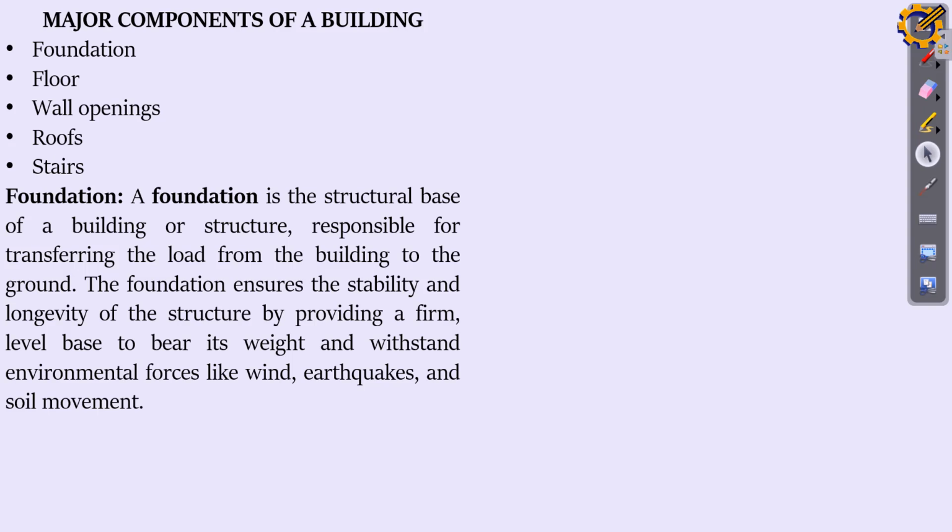Imagine you want to build a structure and you start building on the top soil. If rain falls, it washes away the top soil, and when it washes away the top soil, your building collapses. It's as simple as that. So that is why there is a need for excavation. And the deeper your excavation, the deeper your foundation, the more stable your building is.